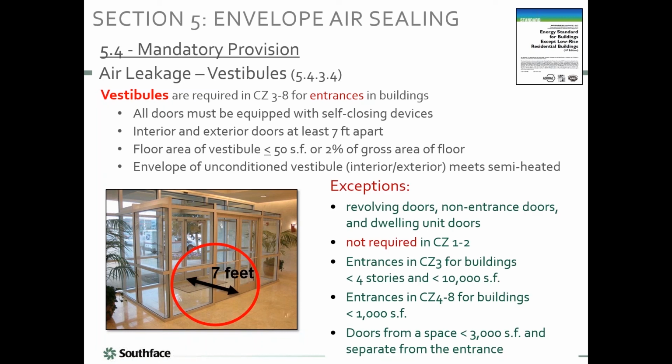Here's a big one. They give you places where you don't have to do it. So not for revolving doors or doors that are not entrance doors or into a dwelling unit. Certainly, they're not required in climate zones 1 and 2.